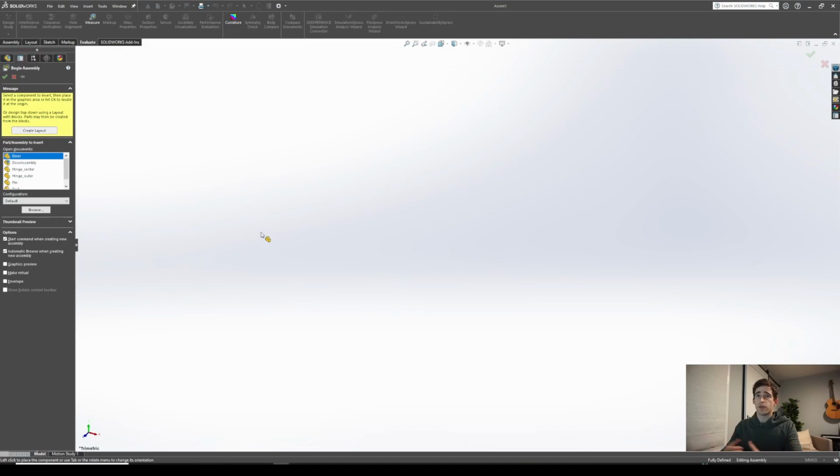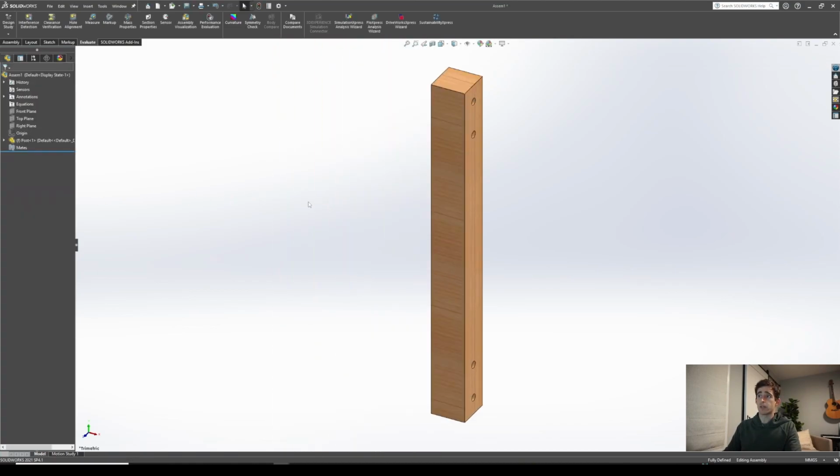And here when you do this, you'll notice SolidWorks opens up an assembly. And if we click our post part and place that in the workspace, we now have the beginnings of a new assembly with post. You'll notice there's an F by the post part here. That means that the post is automatically fixed. However, SolidWorks doesn't necessarily fix the post to the origin of the assembly. And that's an important step to take if you're doing any of the certification exams for SolidWorks.